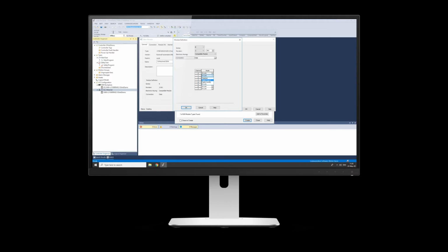Before we said there were 4 connections on the unit and to use a T-splitter. Well, if I set that to digital input, for example, and use a T-splitter on the first port, one half of that would be an IO-Link channel and the other half would be a digital input. But for our example, I'm just going to disable them because I'm not using them. It does give you the flexibility that if you have a sensor that's not IO-Link enabled, you could use the IO-Link master, and then as you get an IO-Link sensor, enable it in here, and it would give you the added benefits.